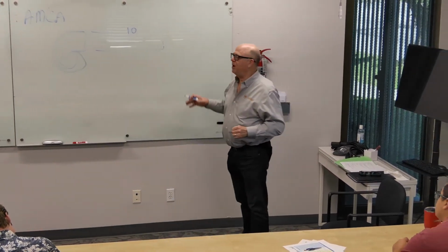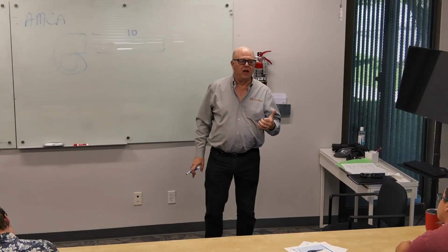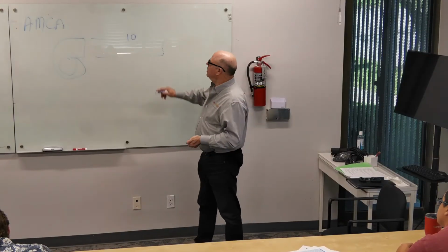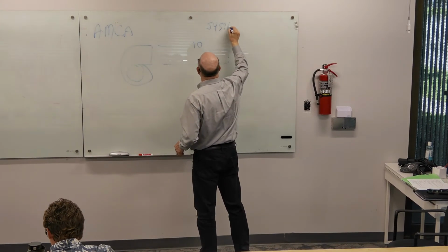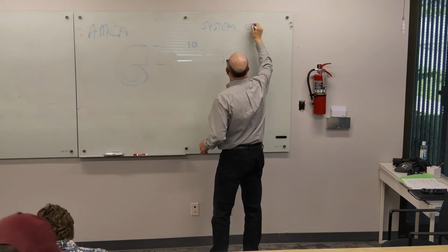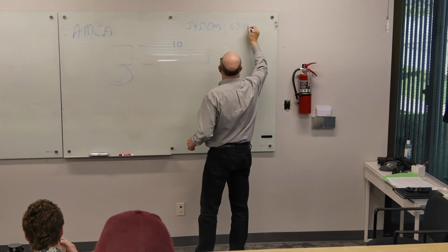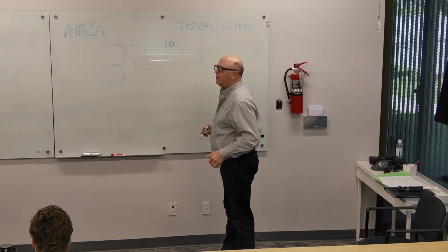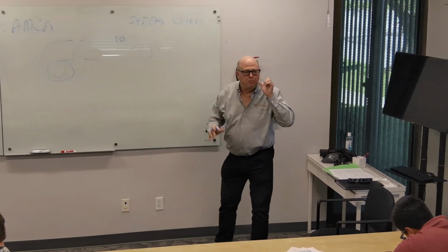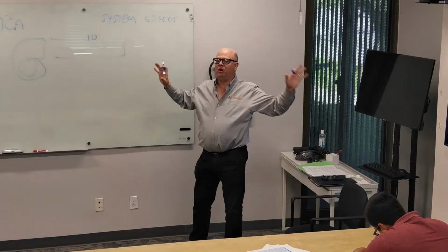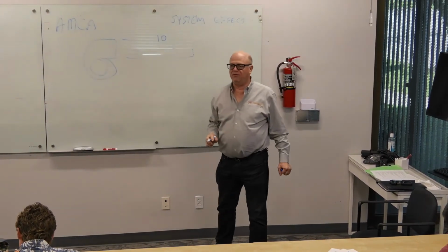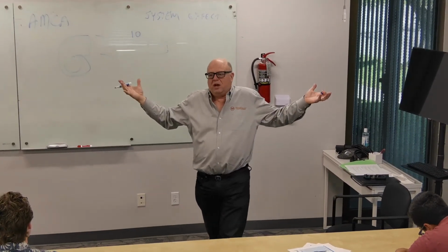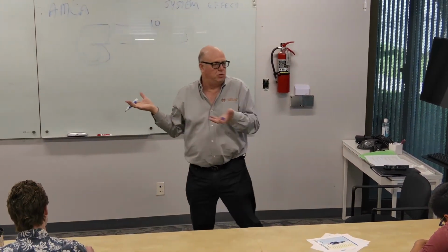But I'm talking about air handlers at the request of various people. And an awful lot of what you do with an air handler is dictated, at least to some degree, if you know what you're doing, by system effect. So if you're building your fan curve, all of your predictive stuff, on having 10 straight duct diameters coming off the fan, because you got to have some standard place to measure it, right? So that's what they do.